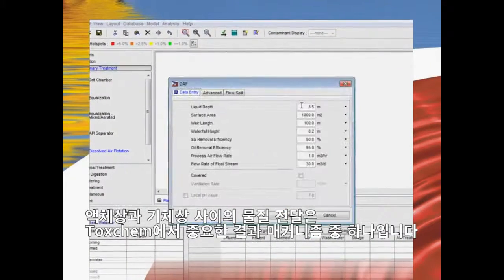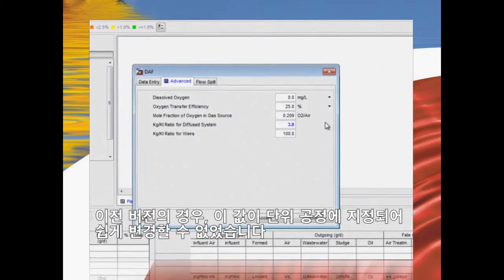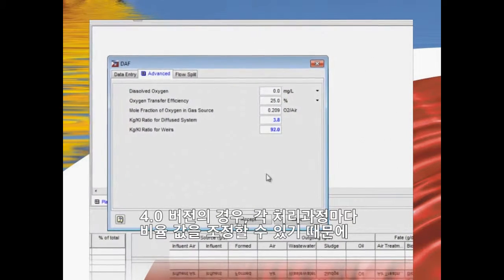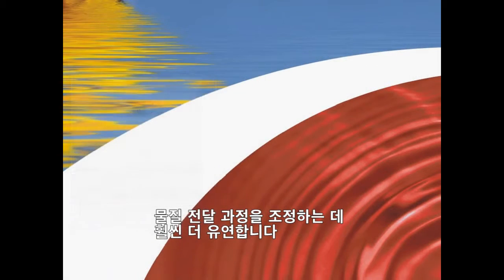Mass transfer between liquid and gas phases is one of the most important fate mechanisms in Toxchem. Many of the mass transfer coefficients are defined as the ratio of the liquid and gas phase coefficients. In past versions of Toxchem, the value of these ratios was specific to unit processes and was hard-coded. Version 4 gives users much more flexibility in the calibration of mass transfer by allowing users to modify the value of the ratio in each process.